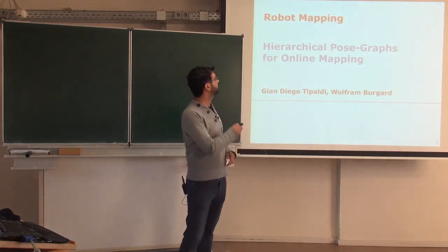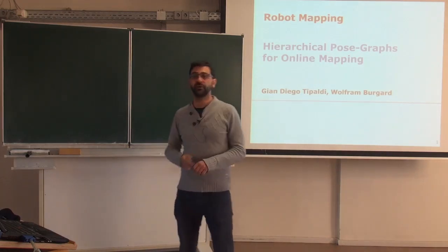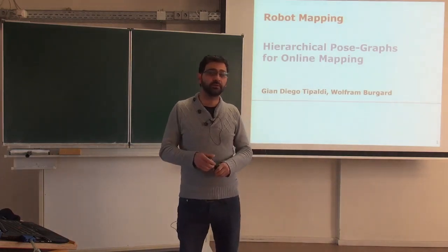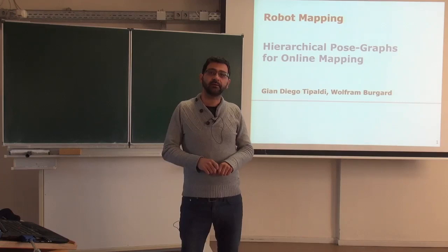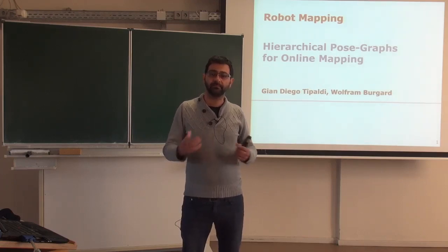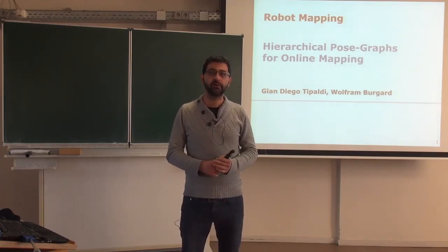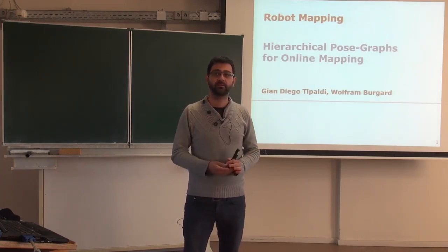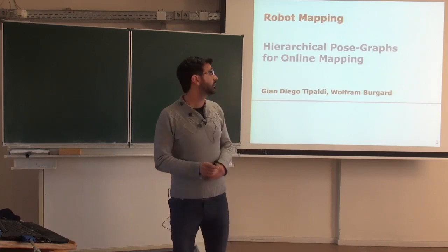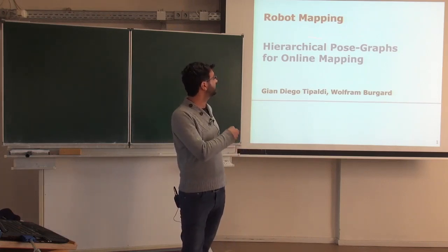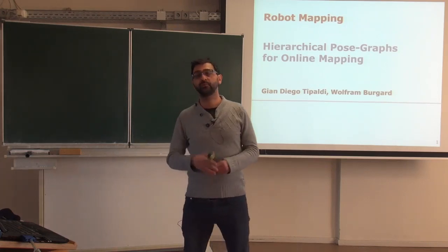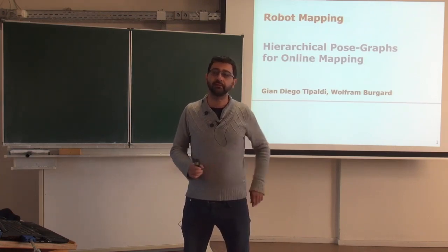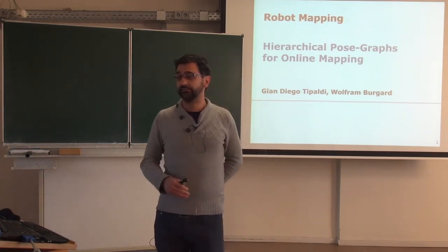Today we are going to talk about hierarchical pose graphs. So last week, for the ones who were here, we discussed the graph SLAM algorithm, the graph-based SLAM, which is a way of using a least squares approach for solving the SLAM problem. And today we see how we can extend it in a hierarchical way to improve efficiency and aid data association.